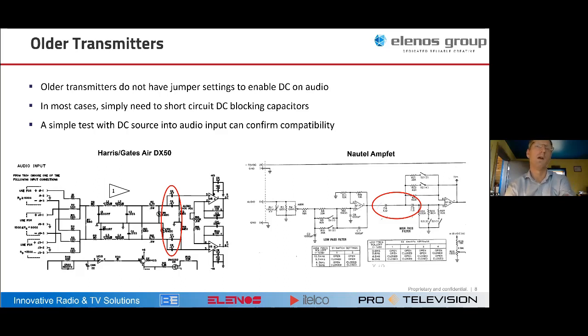And of course, most AM broadcasters now are looking more towards all digital, and it wouldn't be applicable to all digital HD Radio. For hybrid HD Radio, I think probably you could get away with it. They don't really use the carrier amplitude in a hybrid system for much.